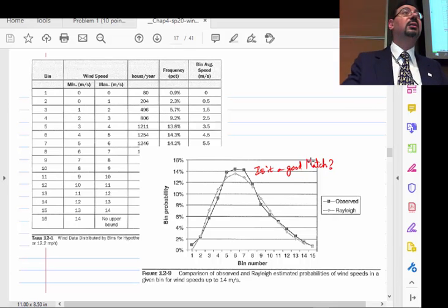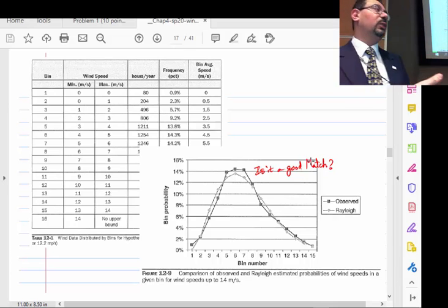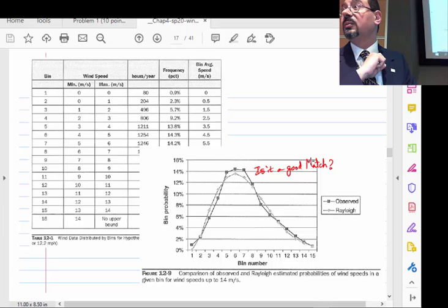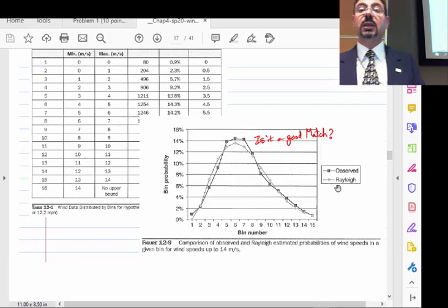So it's not just like I got a wind turbine that's 2 megawatt, give me my 2 megawatt. The question is, when does it generate that 2 megawatt? What velocity does it need to make it run? That velocity is called the rated velocity. When you give it the rated velocity, it will give you the rated power. So when they sell you the 2 megawatt wind turbine, they will tell you this is rated for, say, 10 meter per second. You give us 10 meter per second, we will give you the 2 megawatt. You give us 7 meter per second, and we'll give you less.